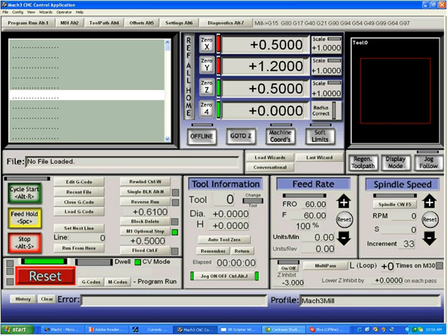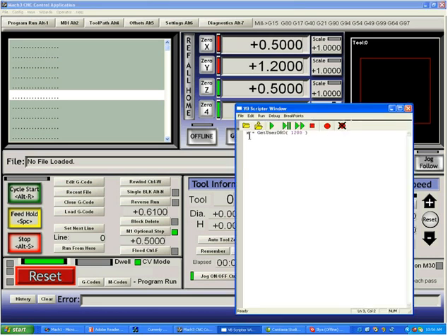So if we bring up our Visual Basic scripter again, and we tell X to take the value of getUserDRO 1200, and we tell Y to take the value of getUserDRO 1201, and Z to be equal to getUserDRO 1202, at the end of this Visual Basic run, the X, Y, and Z will be equal to the values which are in those DROs, and those DROs are persistent. Whatever you type into them, the program will remember from run to run.